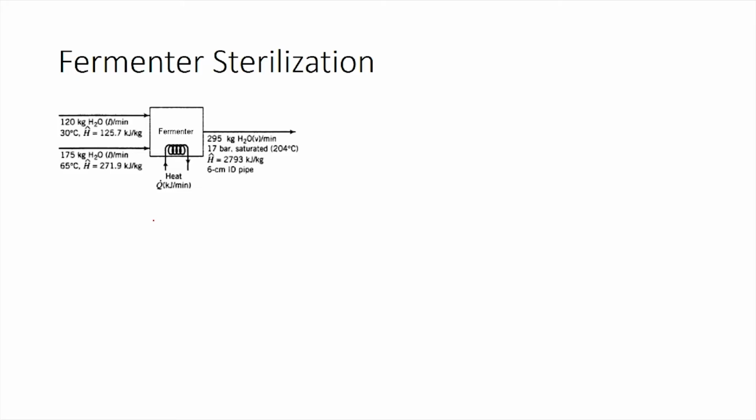First thing is for us to identify volumetric flow rate. How can we convert the mass flow rate that we have into volumetric flow rate? The steam tables give us information not just about internal energy and enthalpy, they also give us specific volume. Using specific volume we can convert the mass flow rate into volumetric flow rate.